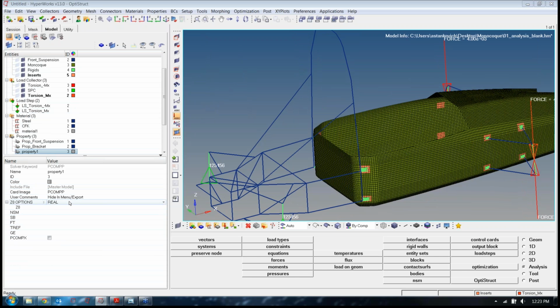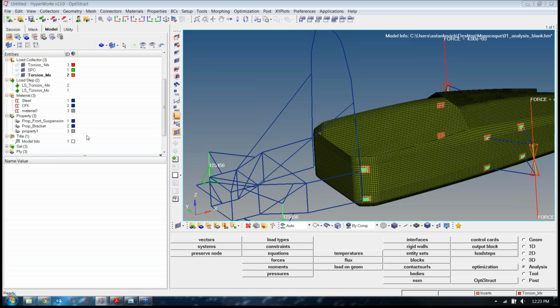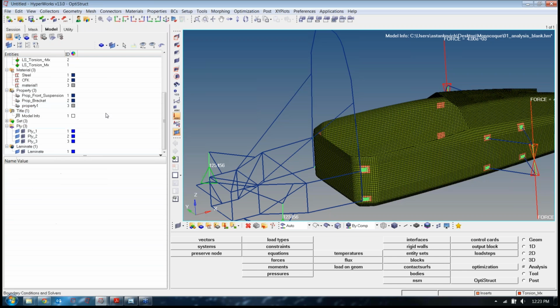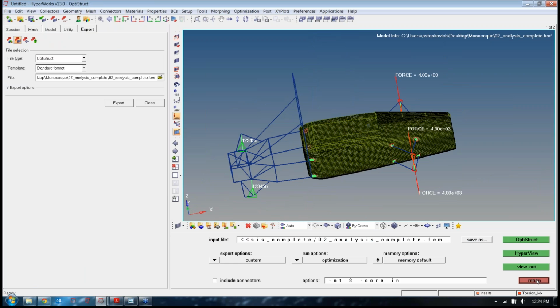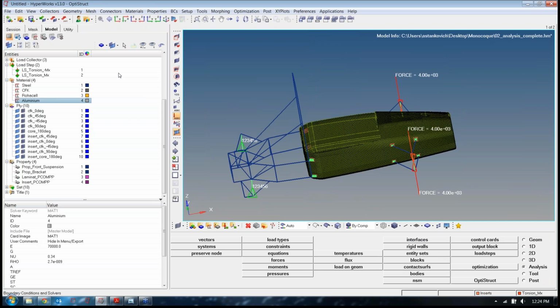And in here, again, there are some other settings. If you want to set a Z offset, or you want to use some type of failure criteria, you put in your failure criteria, and this SB is going to be your shear between layers, so your bonding shear. And so you can put those values in. Once you go through and create this whole laminate, I'll just pull up a completed model here.